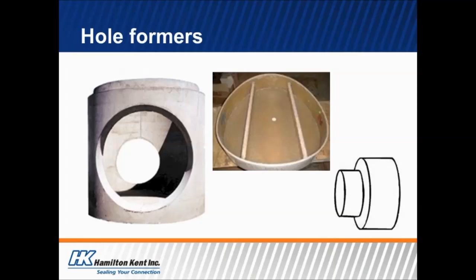But the con of it is that you must know the hole location exactly before the structure is cast. You have to know exactly what the size is going to be, and this delays the delivery process somewhat to a contractor. So some contractors will not be very timely with how quickly they order their structures, and so if it's a custom structure, then that will mean that they have to cast the structure very quickly, and